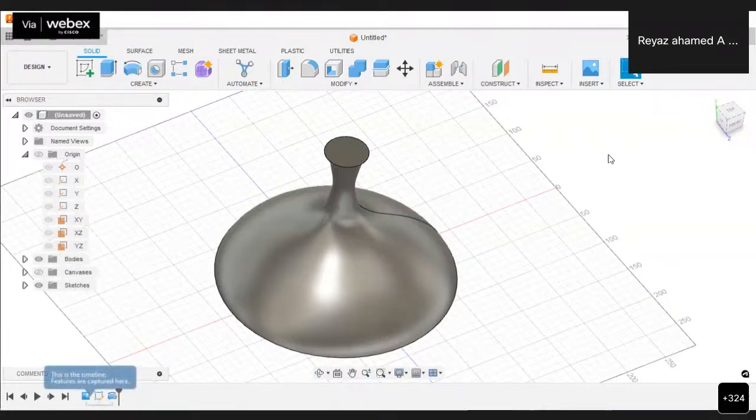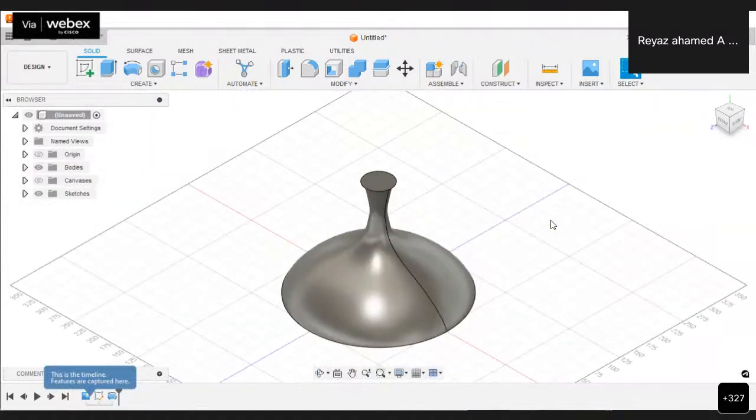So far we have created our lampshade top portion alone, and that too as a solid. So we have to convert that into a certain thickness. We have to convert this total object into thickness. For that, let us go with the thicken option. Before that, let us understand how to change the display settings of the model. See here, there are different display settings options. There is an option called display settings. Let me click on here.